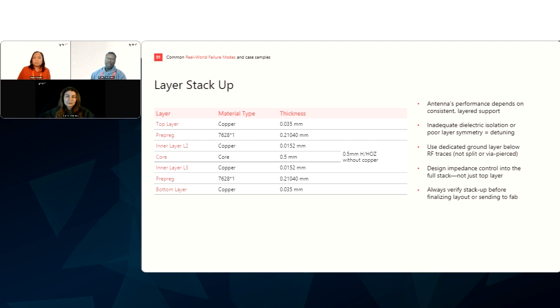But not only that, you could have what we call ground plane current loops, which is essentially signal leakage, because what you're trying to do is create a low impedance path between your RF signal and the ground, essentially. So you have a proper return path for RF currents. So it's important to have a lot of considerations for your PCB design.